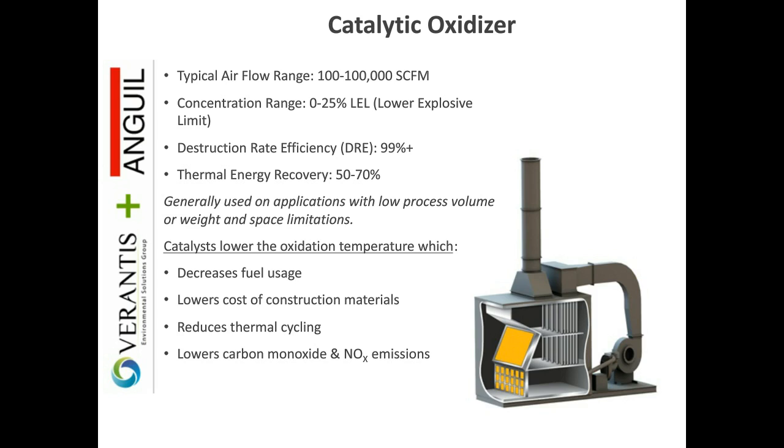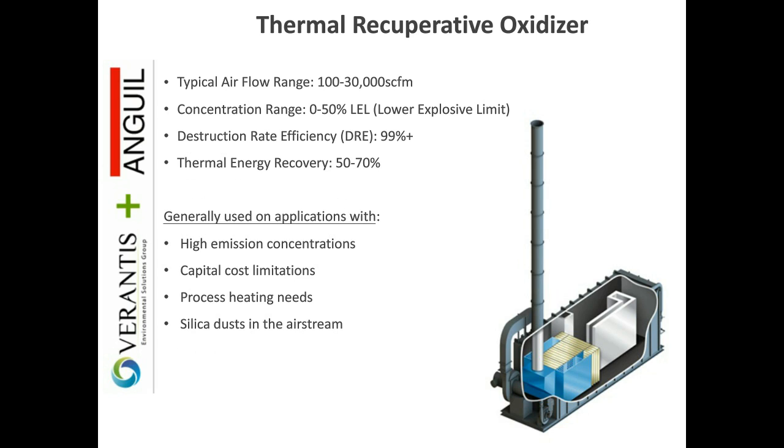A thermal recuperative unit. There's a very niche market for these types of systems. Again, this is a thermal oxidizer, so it does not have catalyst present, and it operates kind of like an RTO, but the heat exchanger, just like the catalytic unit, is much lower efficiency than the RTO, so it's again in the same 50 to 70% range. And because it is less efficient, it can handle higher VOC concentrations, so this unit can handle up to 50% LEL, where the catalytic unit and the RTO are limited to 25%. But again, very niche market.